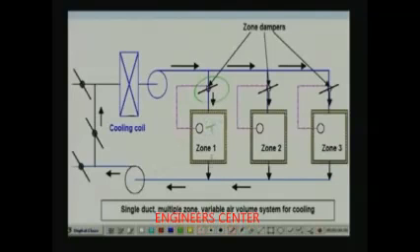For example, if the temperature inside the zone 1 drops, let us say, because of the reduced load, then the capacity also has to be dropped. So, the capacity is dropped by reducing the flow rate through the zone damper. So, the thermostat senses the lower temperature and it closes the zone damper, so that less amount of air enters into the zone, thereby it meets the required reduced load. So, the same thing happens in different zones, that is why you call it a variable air volume system.